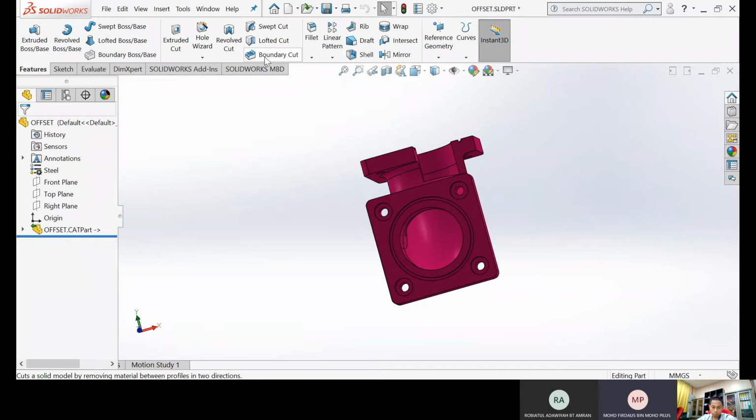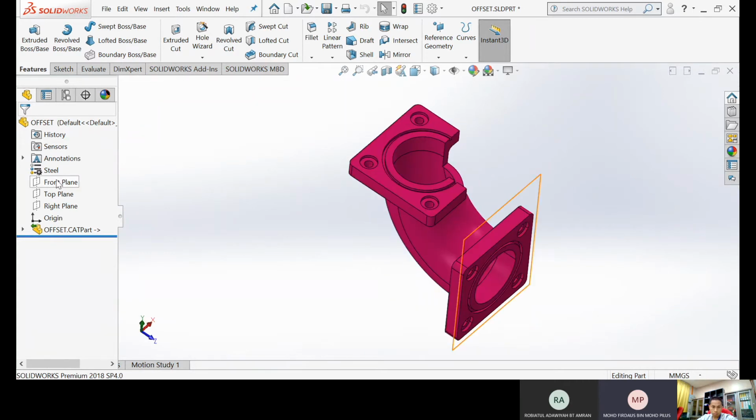And the next is part 7, which is finalize surface. Basically, in this part, it is important to use the front plane to trim all the unnecessary information based on the direction that has been used. We add a line at some point on the surface and create the tangency from the line added, and remove the unnecessary information. So from there, we can see that the tangency can be added to the surface.